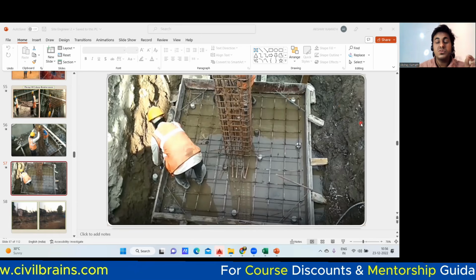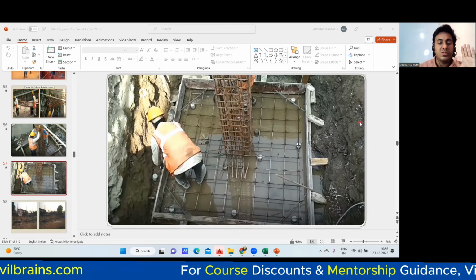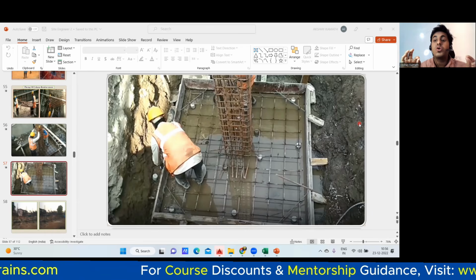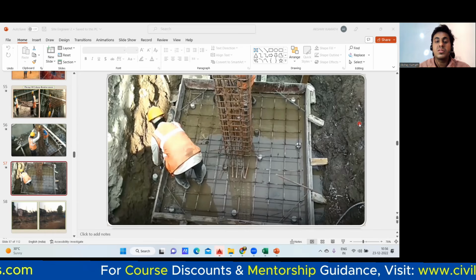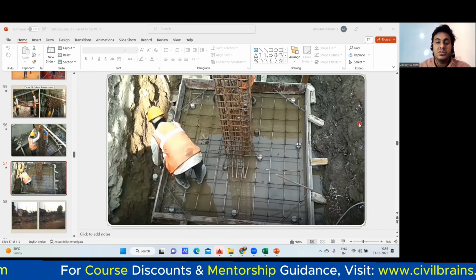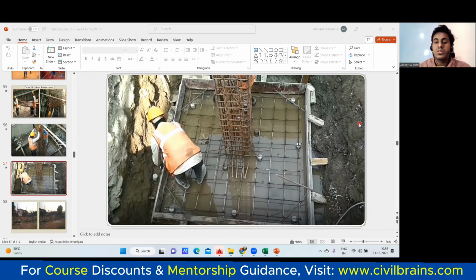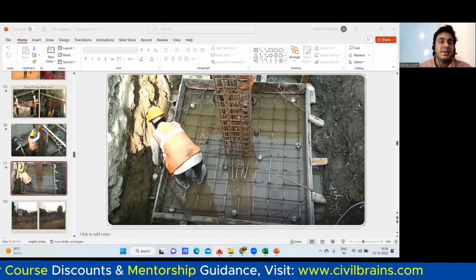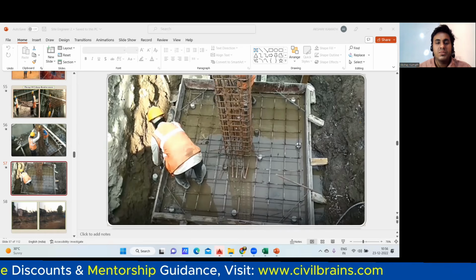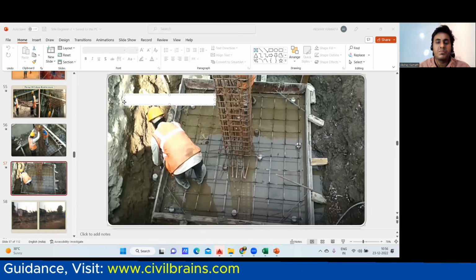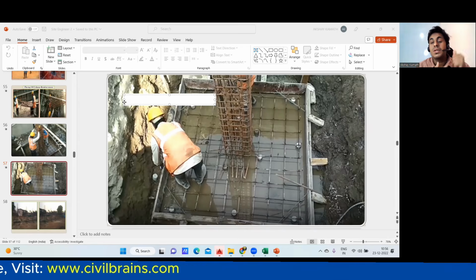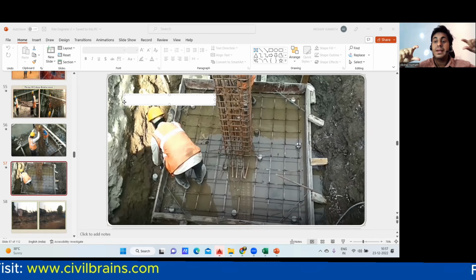And I think with this class, all your doubts, whatever you have, are solved. So finally, whatever you follow on your site, you do that. Now you may ask, sir, I'm running my own consultancy, or I don't have anyone to ask, then what do I do? So what I say is you apply the 2/3 rule, which is a right practice to be done, because that much L is actually not required. If the footing is only 300 mm depth, it's okay. Imagine an isolated footing having a 600 mm depth. In that case, you're just giving 500 mm L. So 500 on left side, 500 on the right side is 1 meter. So roughly you're wasting a lot of steel.